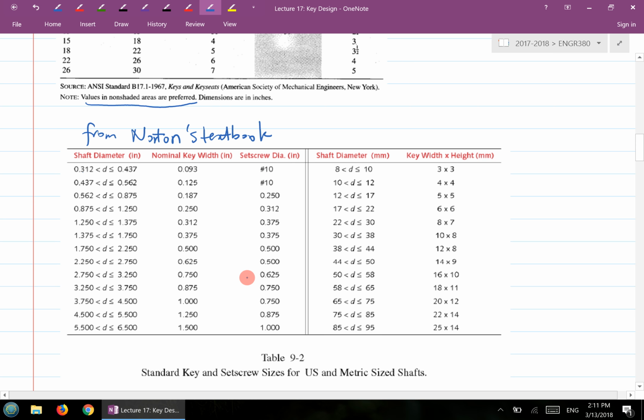Okay, so if you have a gear and a shaft, then you put the key on the shaft, then you slide the gear right onto the shaft, on top of the key. Then how would you fix the gear to the shaft axially? Basically you can use a set screw all the way through the hub, and fix the set screw on the top of the key, so then you can fix the gear or any other component from movement in the axial direction of the shaft.